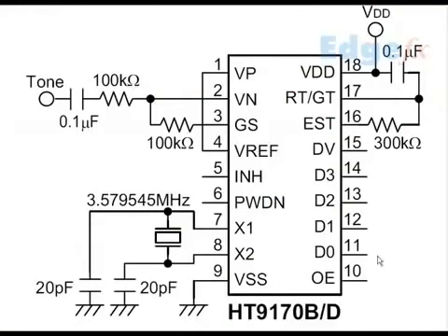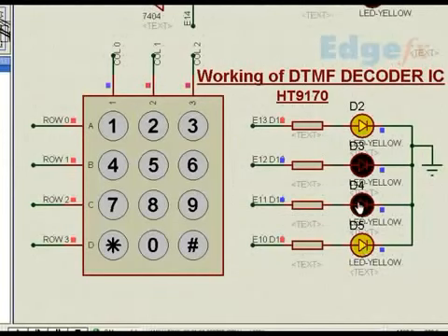From the output, since we have seen that this is a binary output, normally if you have to connect it to some other circuit ahead of it, we use a buffer. The buffer could be an inverter or a simple buffer, but in many cases we use an inverter. If I get 1 0 0 1 from this IC, after the inverter it will be 0 1 1 0. For digit 5, after inverting, it will be 1 0 1 0, which is just the reverse of the arrangement we have, and that is how it is interfaced to the circuit for the program to understand.